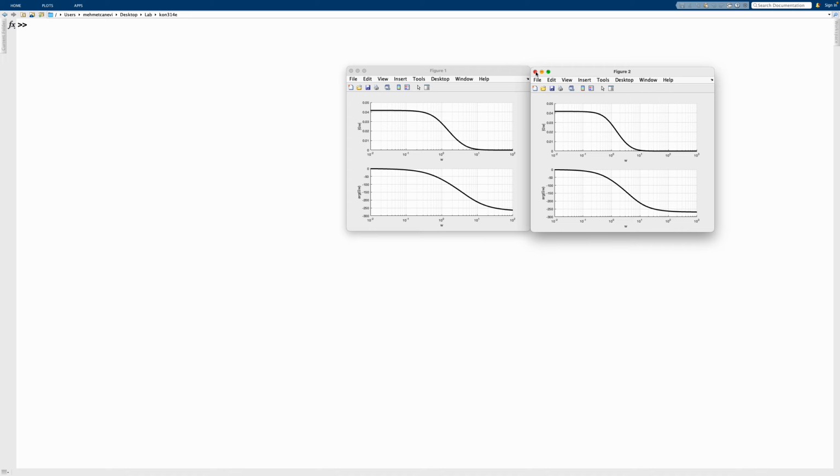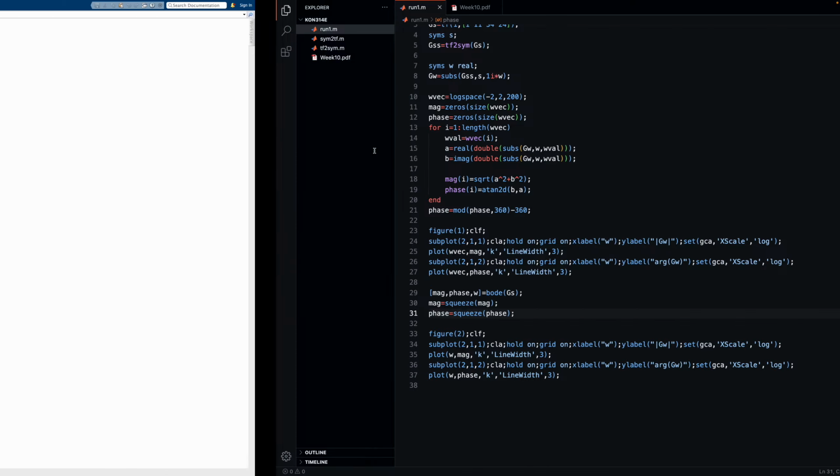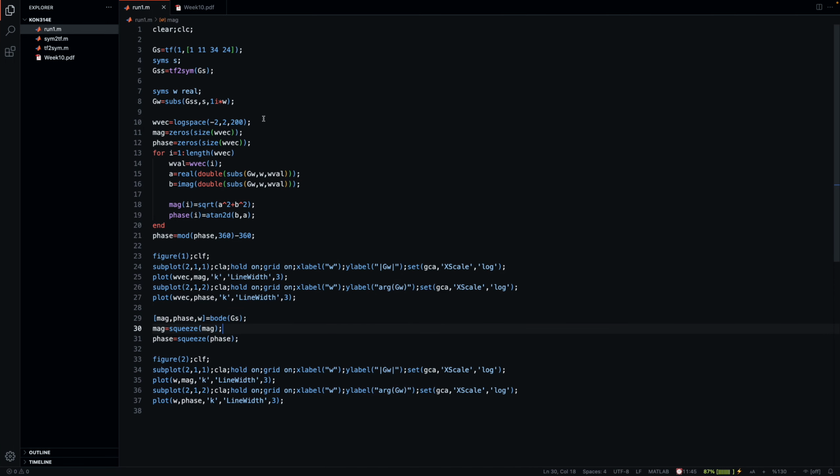So now, of course, let's get rid of the Bode calculations. This was just an introduction to the frequency domain and to show you how we treat transfer functions. We actually don't treat them like transfer functions. We convert them into their Fourier representation, which is basically depending on omega and is a complex number. And then we convert them to polar coordinates. Then we have magnitude and phase, and everything will be about magnitude and phase from now on.